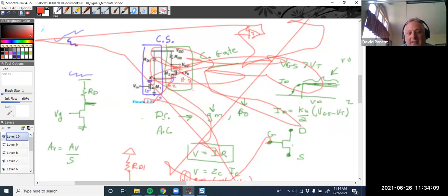And then this transistor being on is just connecting you to this here. So this transistor, when it's just on, is just a current source, and whatever is leaving and entering the node just balances itself out, and ultimately you're back to a common source amplifier. At least that's my interpretation.